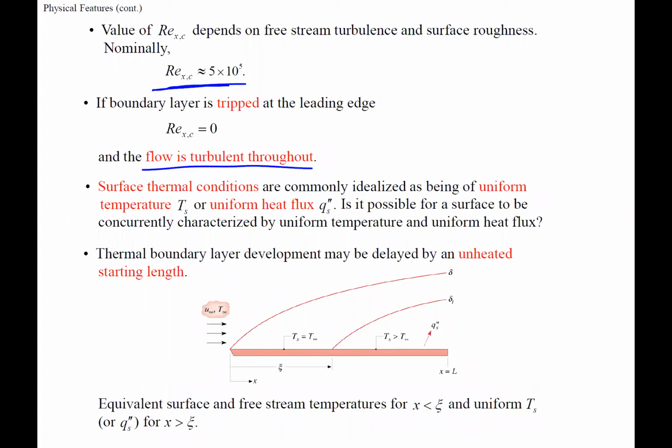When we look at these flat plates, we have two situations. We have uniform surface temperature, or UST, and then we have uniform heat flux, which is uniform surface flux. That's in the case on the flat plate, on what's happening on that flat plate. Are we putting a constant heat flux out? So are we just putting the heat flux, maybe it's a heater, or are we keeping that plate temperature constant to a set temperature? So we have those two different situations.